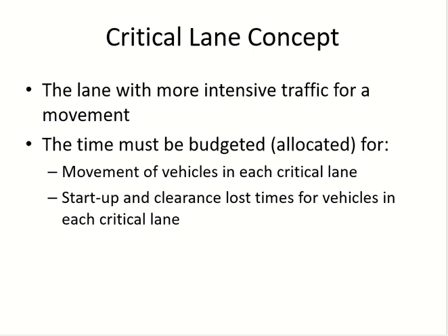Then what to do? You said higher volume. Volumes are equal. Then the one that has a turning. The answer is correct. Yeah. It takes more time, right? So this is how we generally define the critical lane. Not on the basis of higher volume, on the basis of higher time.